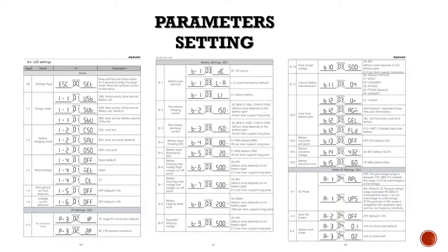If you turn it on and you have not done your grounding, this inverter is going to bring up an error, because the detection function checks whether your grounding is properly done. Because we don't want to give you all that, we put it off by default. Leakage current detection is also off, but if you are sure there's no leakage current, you can put it on.